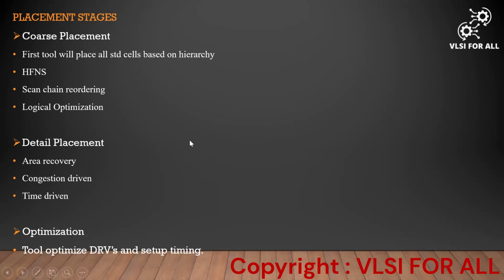Once the standard cells are placed legally, it will look at how much area it is going to utilize, compared to the earlier coarse placement stage. Now it will take area utilization into account. Based on the area-driven placement stage, as we discussed earlier, it will take all the flops which were communicating near each other in order to reduce congestion and get better timing. Based on all those algorithms, the tool performs one more round of placement iterations in a number of phases. In each phase, it will have some number of iterations. Ultimately, that placement will be done in the detailed placement stage.